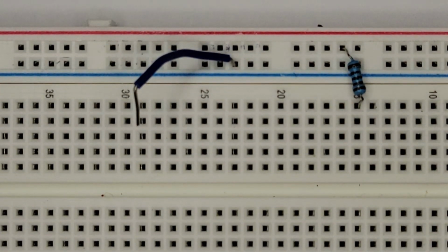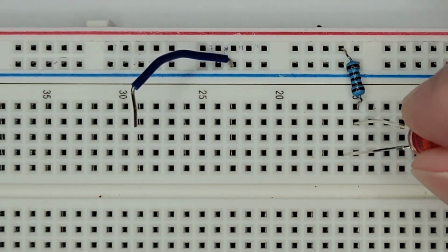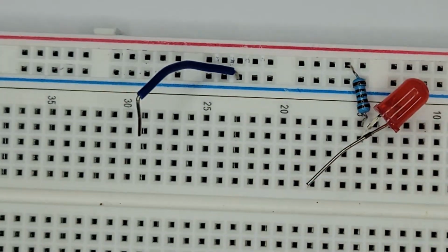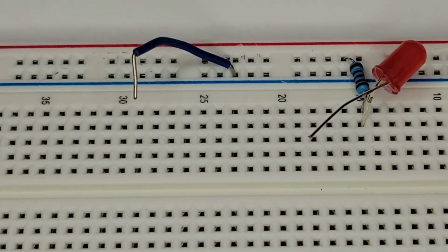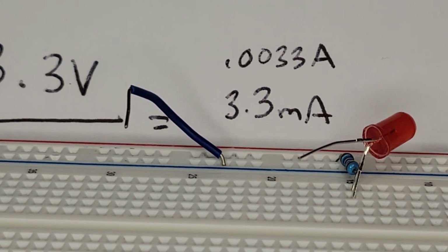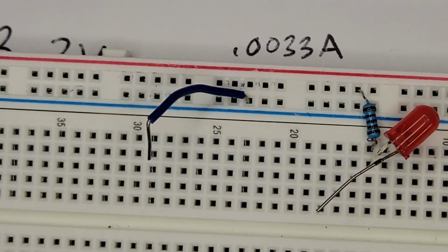All right, so let's plug in his long lead, the positive, to where the resistor is bringing in that power. And then we can also kick up this guy so that we can connect it manually and take another reading to make sure that our milliamps are still at a level that we want. So I'm going to get my meter again, put it back. Let me zoom out.